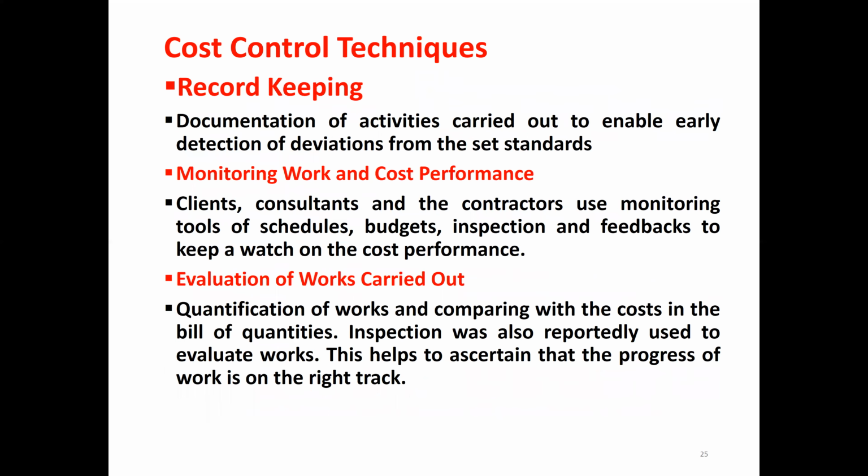Another technique for cost control is record keeping: documentation of activities carried out to enable early detection of deviations from the set standards. Another technique is monitoring work and cost performance. Client, consultant, and contractor use monitoring tools of schedule. They monitor the schedule, the budget, and inspection and feedback to keep a watch on the cost performance.